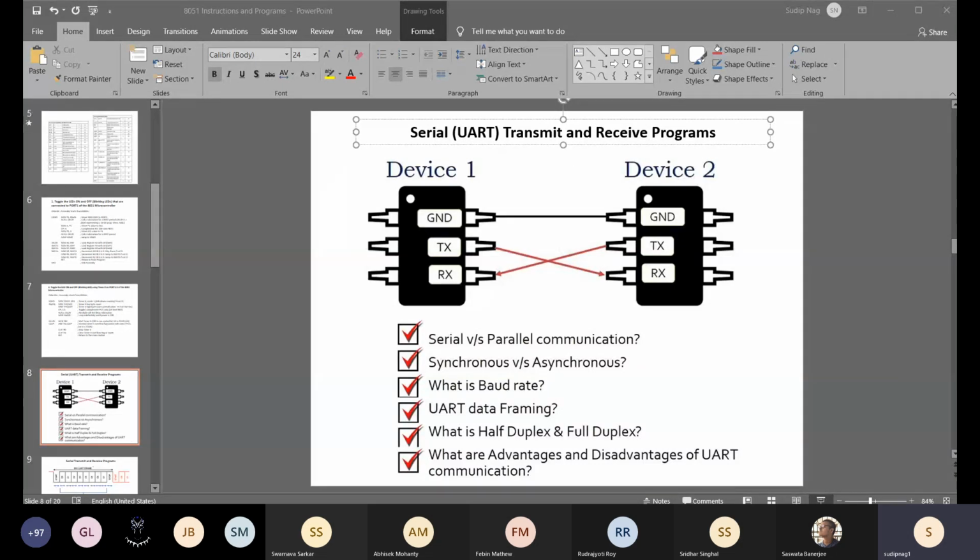As you understand through circuit analogy. Now, looking at TX and RX, TX is the transmit pin, which is the output pin for a given microcontroller, and RX is the receive pin, which is an input pin. So output TX from device 1 is connected to input RX of the second microcontroller, and vice versa for the other two terminals.